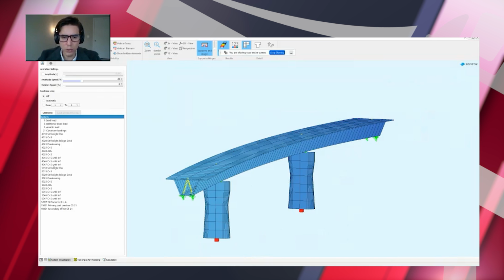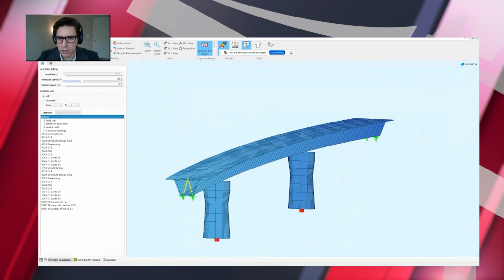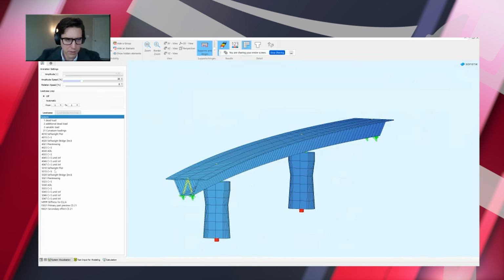But what happens if we want to check the bending moment only for self-weight, or only for pre-stressing, or only for a certain creep and shrinkage stage? We need this to run our combinations and do our design checks. So that's why the program also provides these individual results and stores them in this 5000 series. So let's go ahead and click through the accumulated results first.